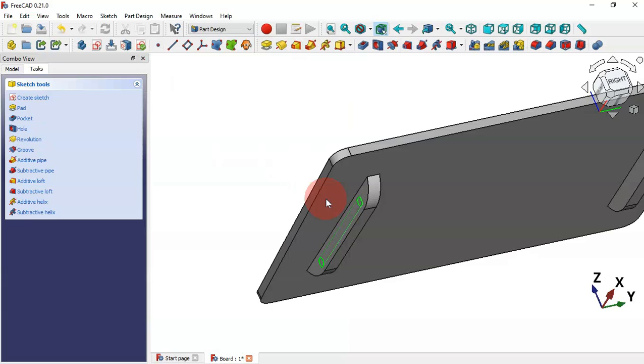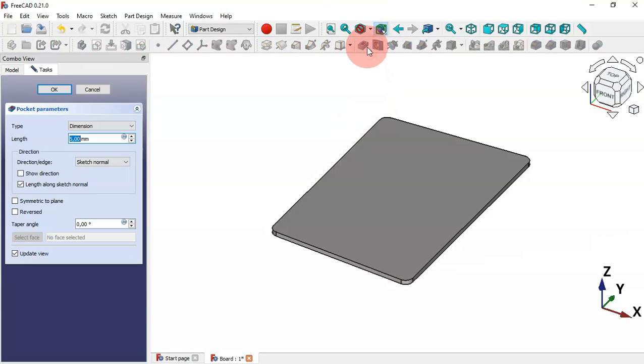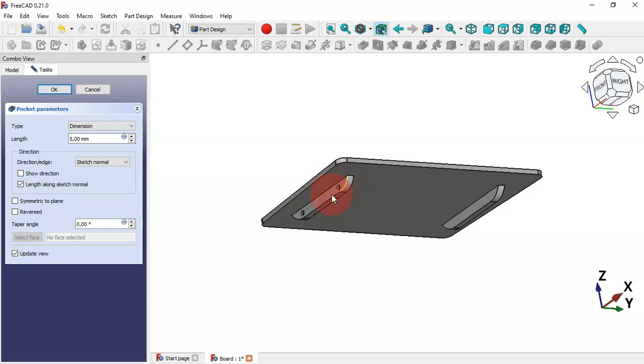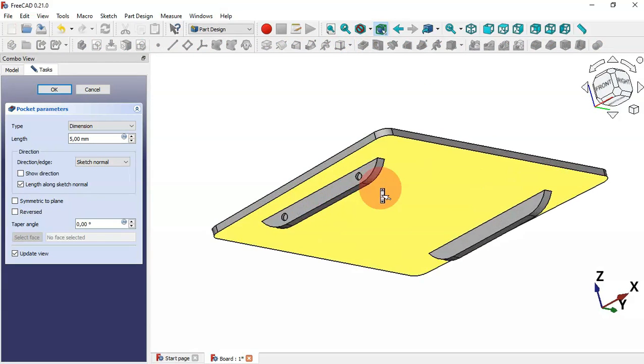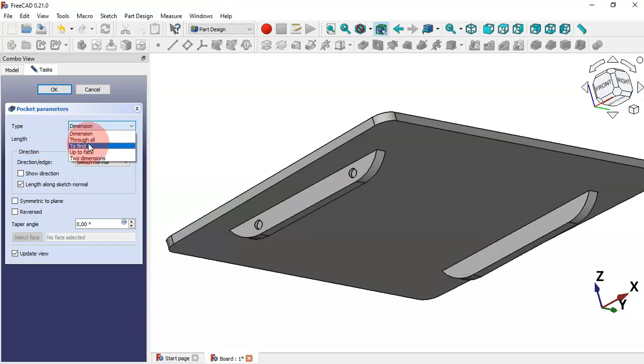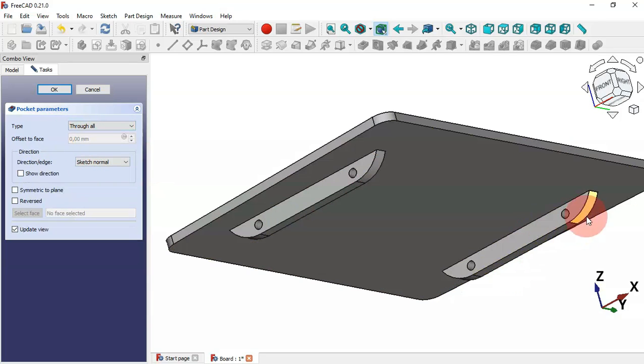And now skip 2 times to leave the sketch, and let's create a pocket now. Press home and click on this icon. As you can see, we have 2 holes here. Okay, so let's change the type to triangle, and as you can see, we have holes here.